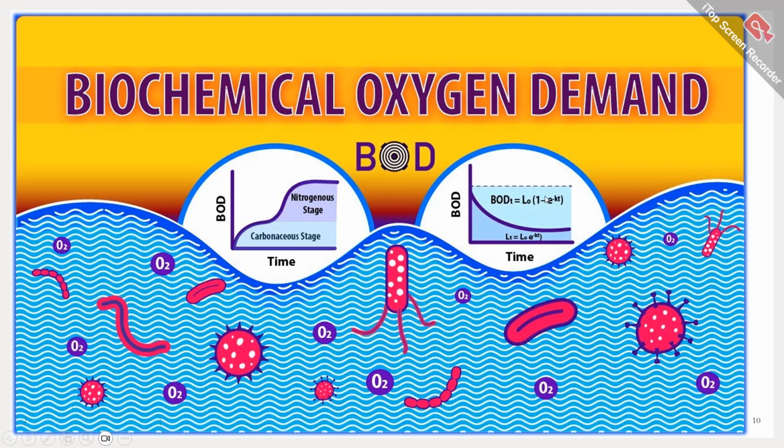And in this case, if we just put here 0, then BOD_t becomes L0. Sorry, the upper portion of the curve is t equals to 0. At t equals to 0, it becomes L0. So as the time progresses, t runs from 0 to infinity, the BOD decreases with time.